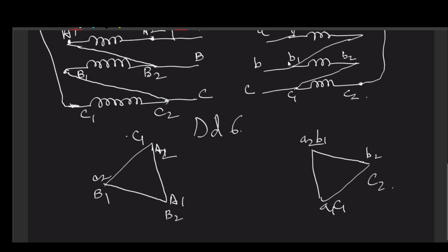One more thing here you should note that we are assuming that the transformer primary and secondary, they are in phase. Here we are not considering the polarity while drawing this phasor diagram. We are considering that they are in subtractive polarity. That means whichever primary side voltage you will get here, the secondary side voltage will be just a similar phasor of same orientation, only magnitude wise different.